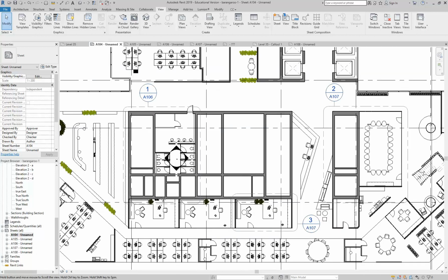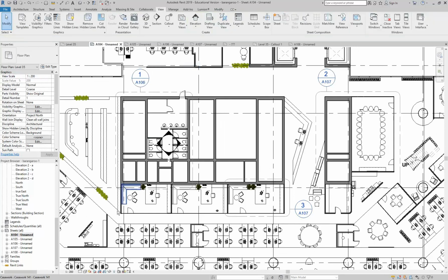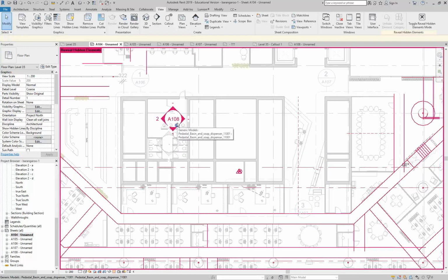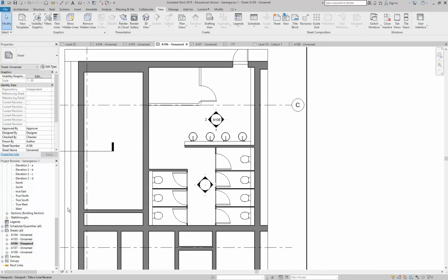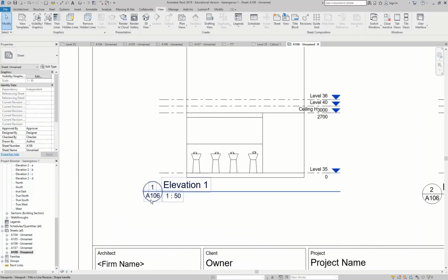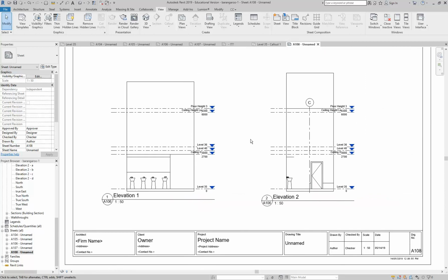Okay, so just so it's clear, all I did is hide this on this sheet that I didn't want the reference coming from. So this is sheet 104. By hiding it on sheet 104, it picks up that it's also on sheet 106, and that the tag is visible on sheet 106. And so therefore the reference now is to sheet 106. That's genius. So the programmers at Autodesk, Revit Corp, do some really clever things like that occasionally, which aren't what the software would want to do, but they've overridden it and said let's make it do what it should.